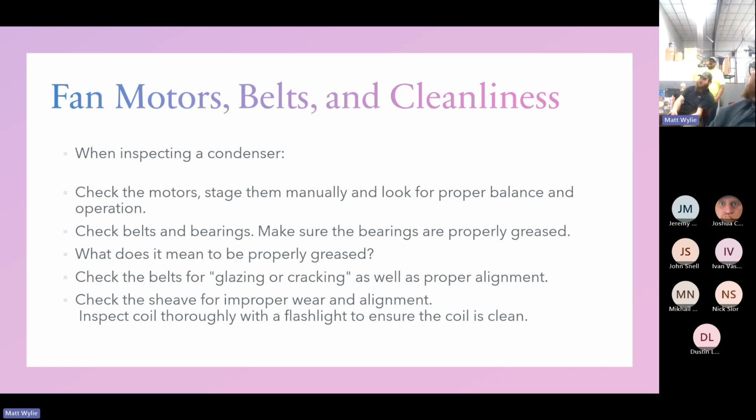I like to check subcool on water coils too, not just water outlet, but subcool. I was actually working on some Stolting units, got called to West Yellowstone, and all their Stolting units were water cooled. They had somebody come in and install an ice machine, and all of a sudden, none of their Stoltings were working. They stole the water off the same line, and the ice machine sucked up all of the water every time it kicked on. They weren't happy to find out that there's nothing I could do except turn off their ice machine.